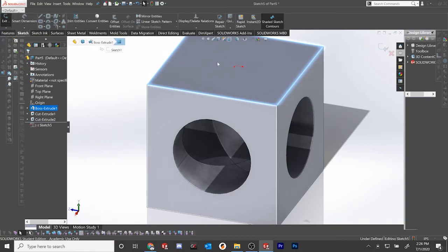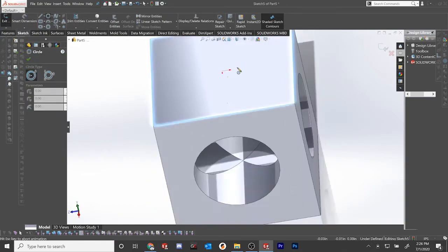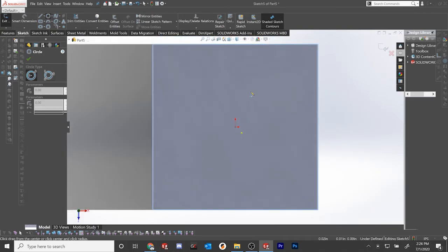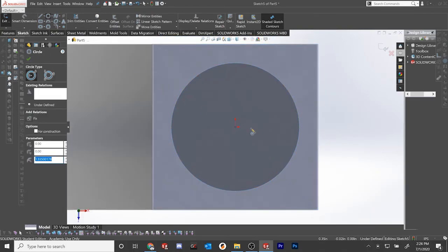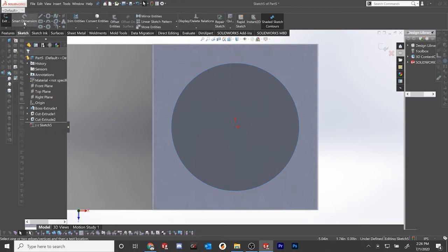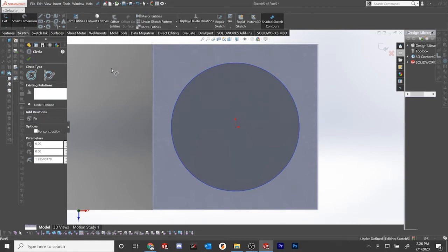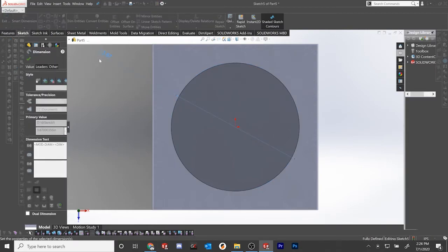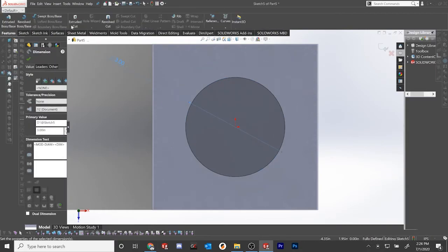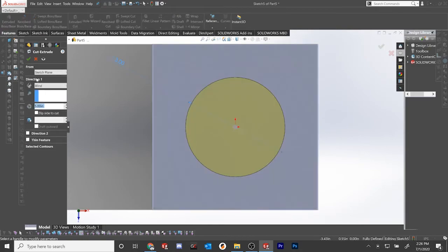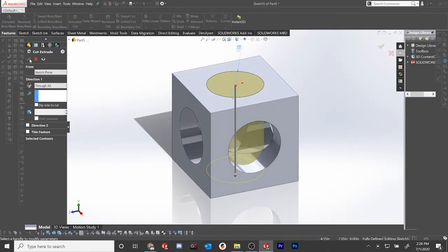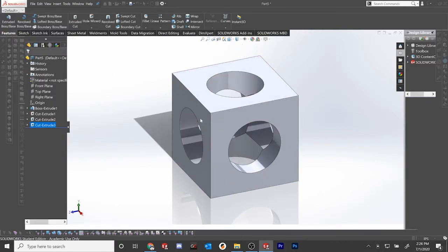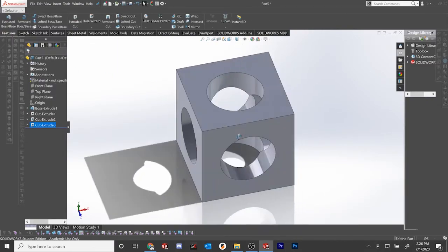and so now I'm in a sketch, press on Circle, Control 8, create the circle by fixing it to the origin, then Smart Dimension it, select the circumference, click elsewhere, 3, enter, then features, extruded cut, through all, and check. So now I have my body and I've applied some other features to it as well, like these